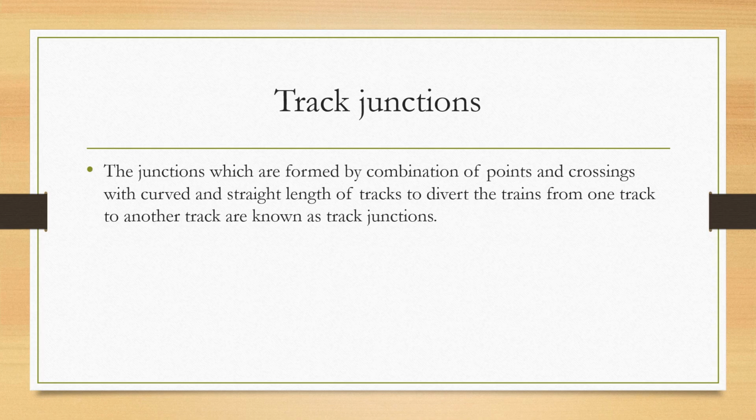Inspection of points and crossings. Gauge. Gauge should be checked throughout for a distance from a little in front of the toe of switch to a short distance behind the heel of crossing. Tongue rails. These rails should have proper fixing with their respective stock rails and must have full bearing on the slide rails.